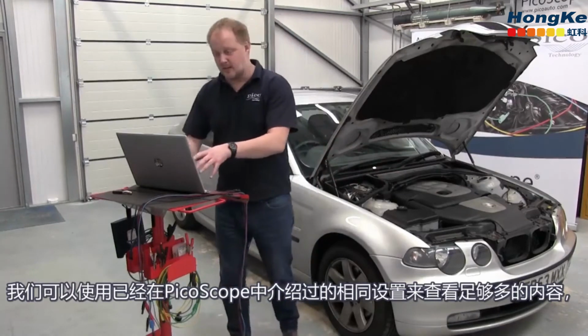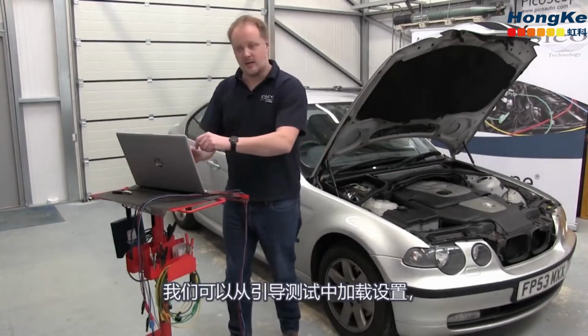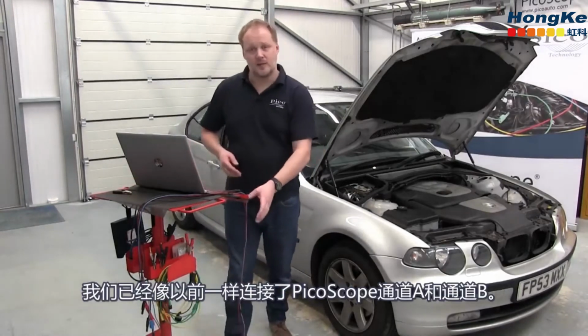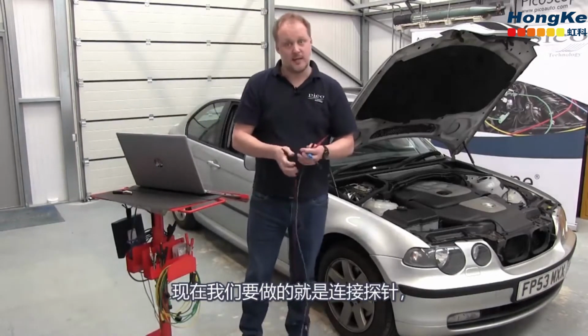We can use the same settings that we've already described in Picoscope, so we can just load up the settings from the physical layer guided test. That's all good. We've got Picoscope channel A and channel B connected as before, and now all we need to do is connect our probes.